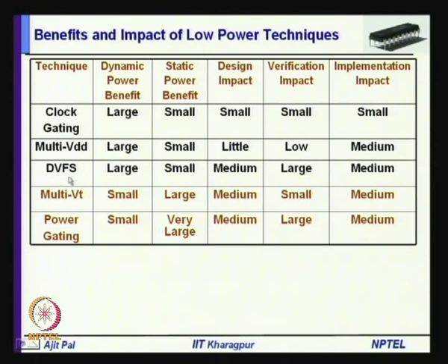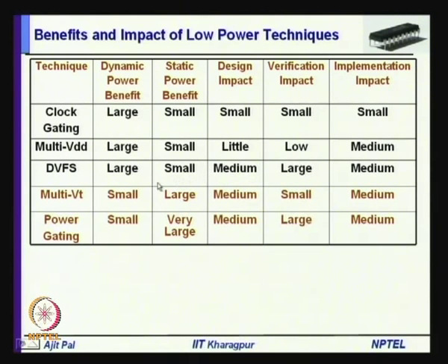However, dynamic voltage and frequency scaling can be used in applications where the circuit or the system requires different performance levels. That means sometimes you require 10% performance, sometimes 20% performance, and so on. In such a case, you can use dynamic voltage and frequency scaling, and again this has a large impact on dynamic power, small impact on static power, and design impact is medium, because you have to modify some parts of the circuit,